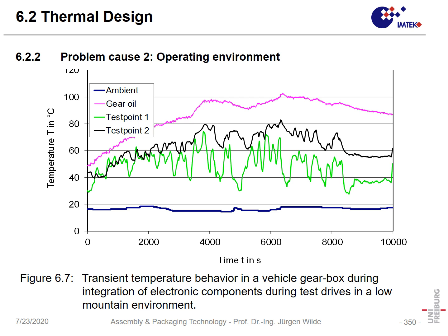So it goes up, the car is heating up, but also depending on the mode of driving, there is some variance of temperature. And when we look at just test points where we wanted to install electronics, we can say, okay, it's quite variable and temperature goes up to roughly 80 degrees centigrade. So we must take care when we make a design of the environmental temperature. It is important that this temperature comes in addition to the dissipated heat temperature inside the device.